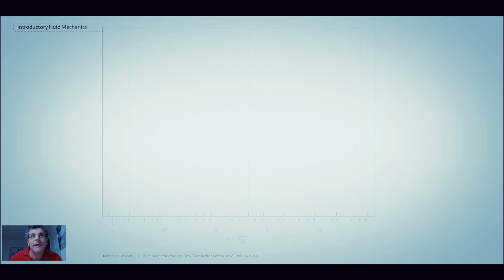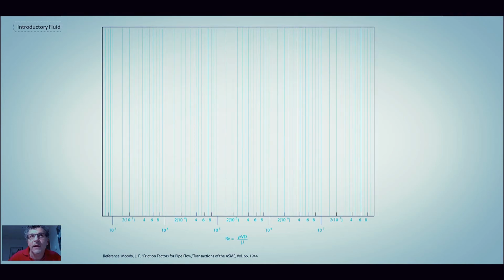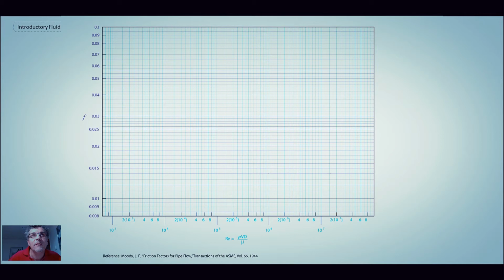The Moody diagram begins with Reynolds number plotted in a logarithmic scale on the horizontal. And then to the vertical axis, we add the friction factor. And so there you can see the friction factor. And then when we put in the relationship that we just solved for, you can see the green line, and then you extend that directly, and that goes into the transitional flow regime. So that is the early construction, I should say, of the Moody diagram, and we will revisit that once we have an expression for the friction factor for turbulent flow. But that is a diagram that engineers use quite often. They either use the functional relationship or the Moody diagram.